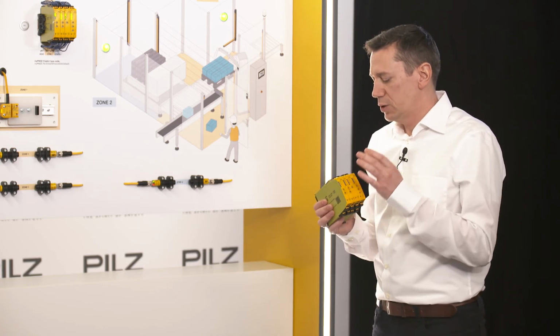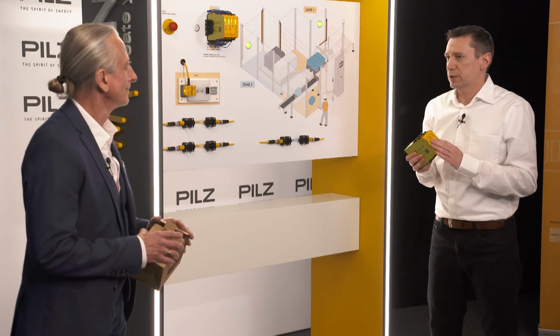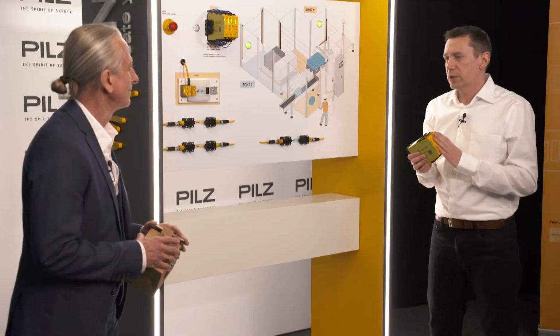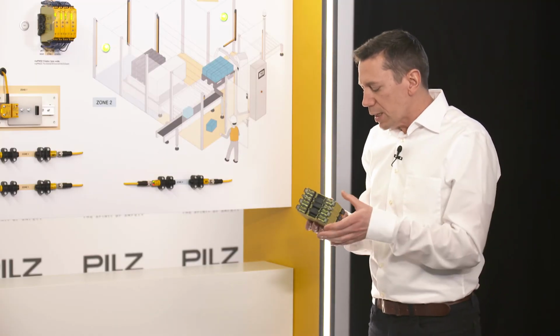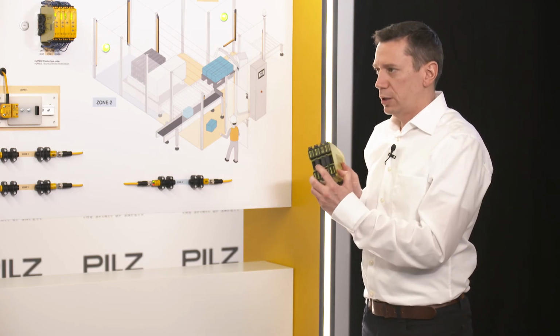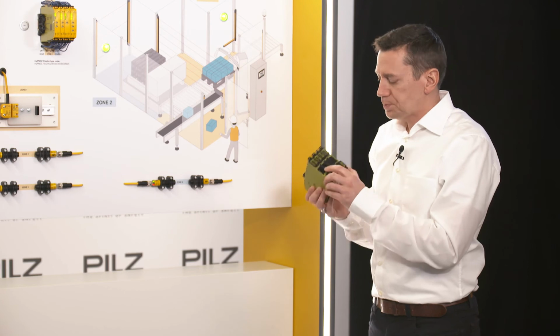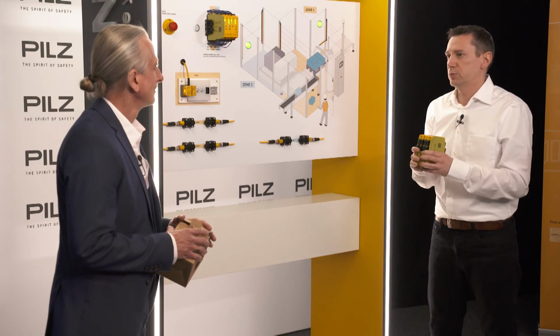The second feature, we have one power supply on the head module for the entire system. That means I only have to connect the power supply once in the head module, the other modules are supplied through it, and I don't need any additional wiring here either. In addition, to save cross-wiring between the modules, we have bus connectors on the back of the modules. All communication between the modules is done via these bus connectors.